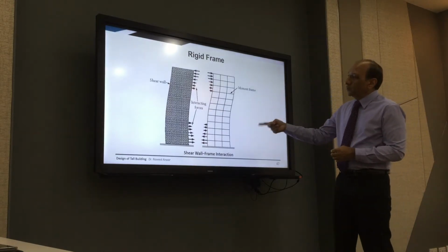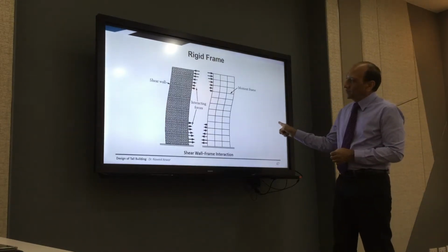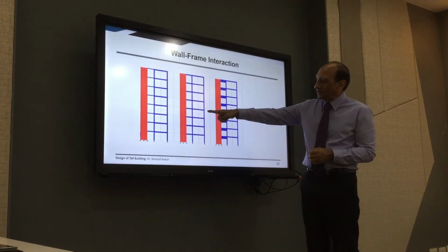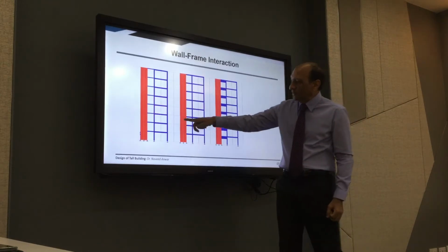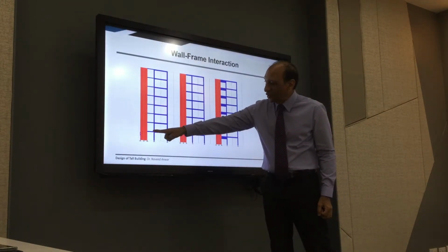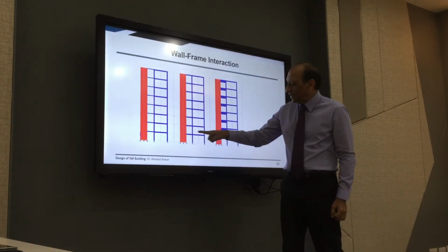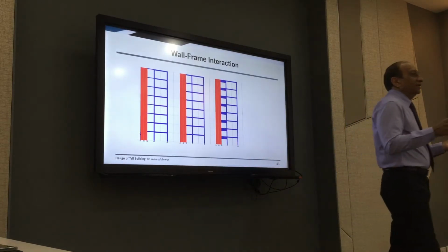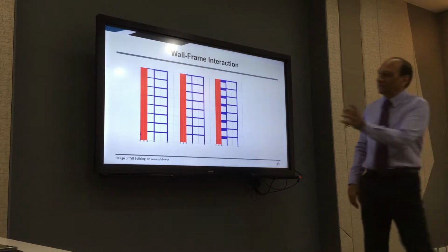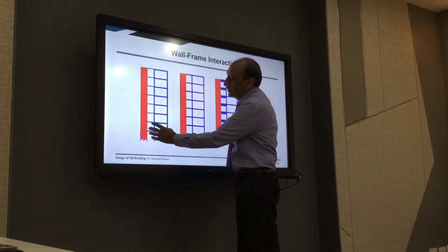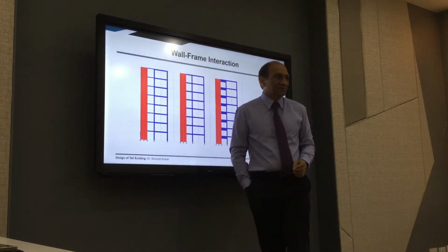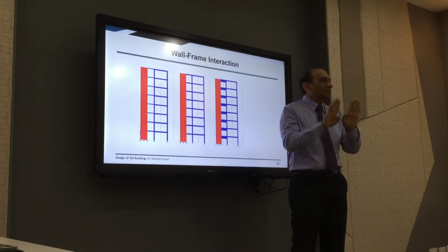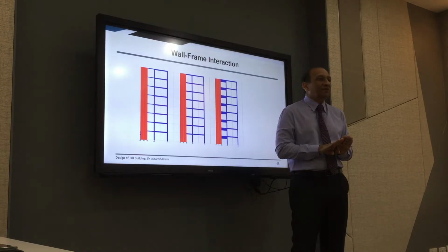So this was observed by some people a long time ago, and now if I do that, I have a frame and a wall, and here I connect it by a small link, medium link, and large link. So then you can see two effects coming together. In the first one, only the interaction effect will be there, the deformation interaction effect, but no spandrel effect, no outrigger effect.